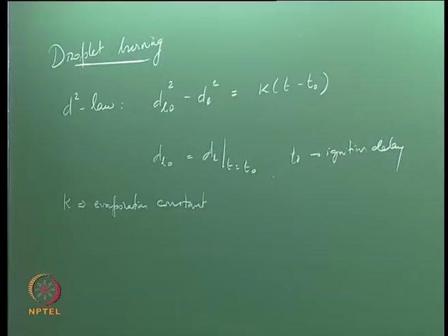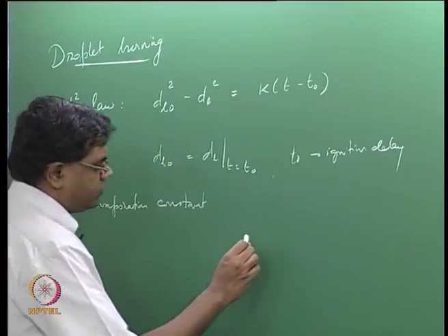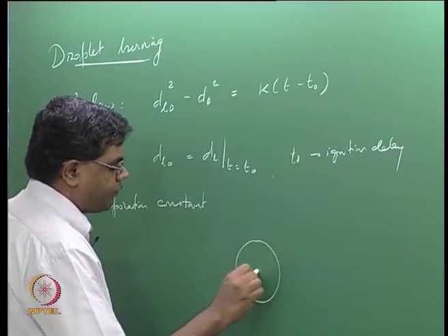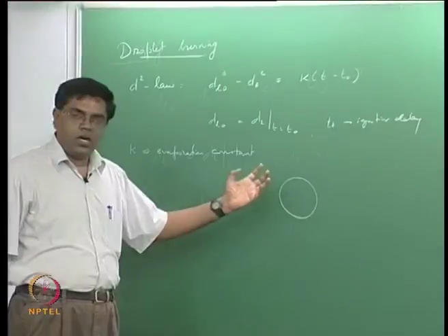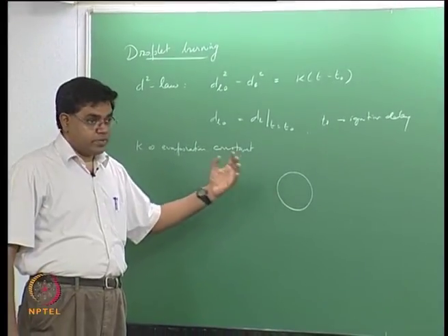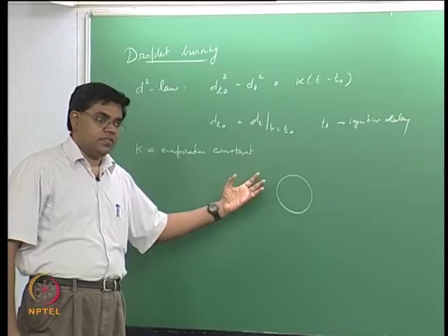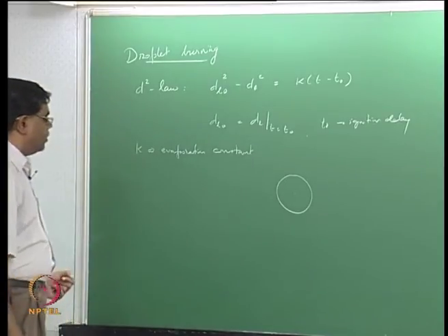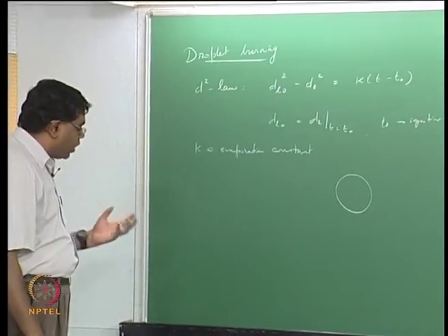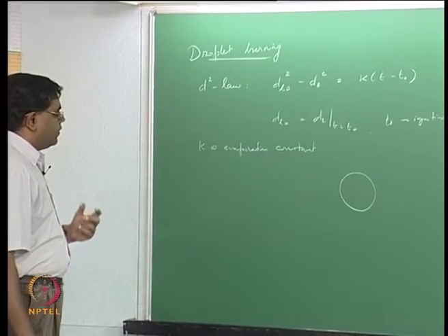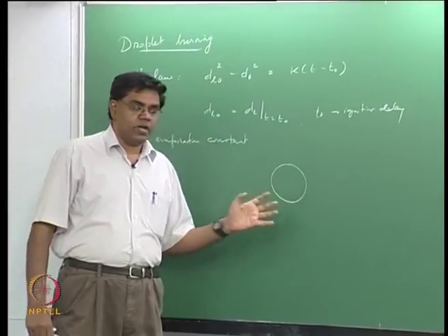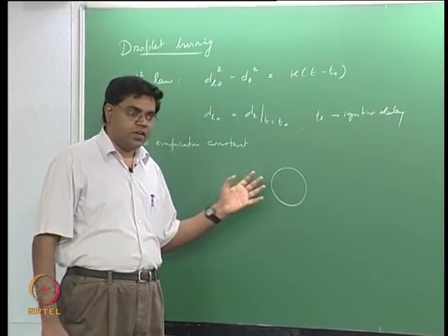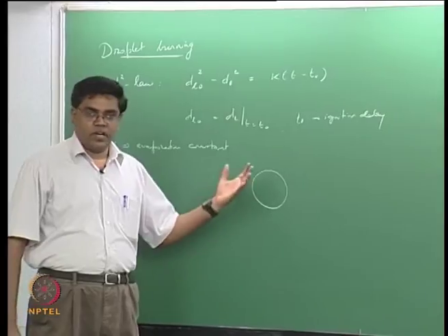So the framework here is that we now assume that the droplet is spherical. It's not a bad assumption considering surface tension effects that try to keep the droplet spherical below a certain size for a given droplet, given liquid. So this is not a very bad assumption at all. For example, if you're looking at droplets of the order of 10 microns or even 100 microns, they are reasonably spherical even in a gravitational field like what we face on Earth.